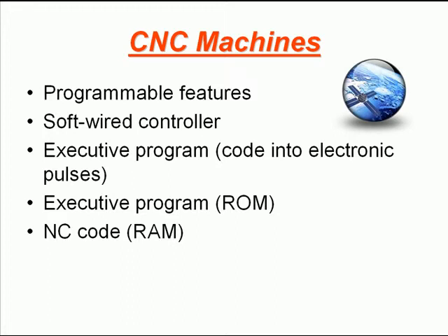You had to use certain tooling, and you had to use statistical process control to make sure you changed your tooling on a regular basis so it doesn't get too dull and start damaging the material or the tooling even more. And then you wanted to tell the machine how thick the material was and what type of material. If you're going to bend the material, you had to tell it the K factor.